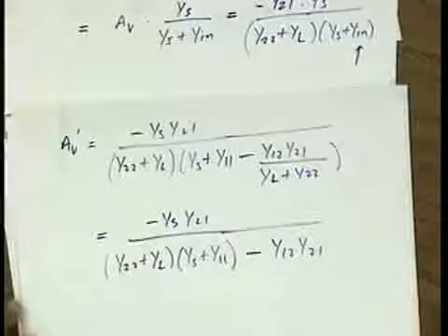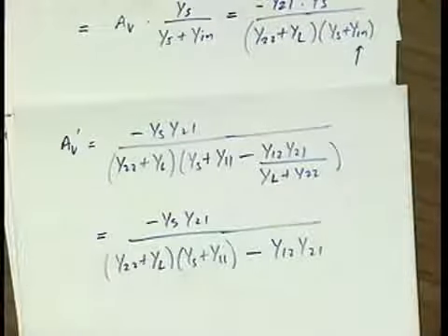Question? So the devices that we model with two-port network should be linear, or they could be any? Yeah, that's actually a very good point. Two-port analysis is only valid for linear circuits. In other words, we said that V1 and V2 is a linear function of I1, I2. That's only true for a strictly linear system. So if you have a nonlinear circuit, you have to linearize about an operating point. And once you linearize about the operating point, then the representation is only valid for small signals. Okay, good question.